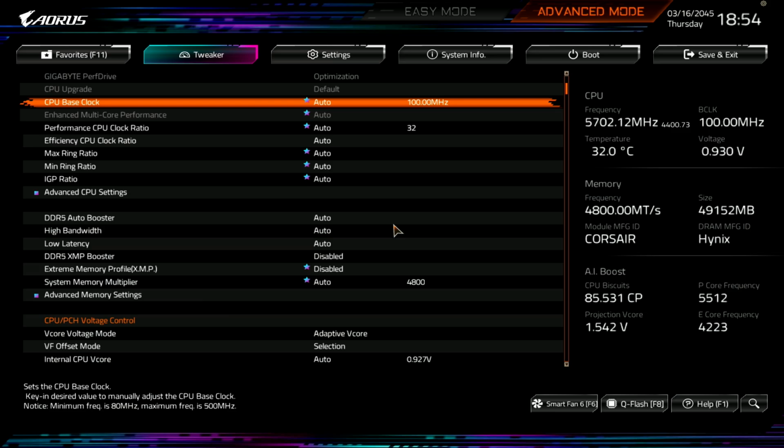But again, the one takeaway I want you to have from this video is that you don't need to turn off CEP to undervolt. If you're undervolting and CEP is ruining your performance, you're not undervolting correctly, basically. You should stop doing that and look for a different way to offset the voltage. As far as I know, every LGA 1700 motherboard that has voltage offsets available should allow you to adjust the vid offset, and that won't trigger CEP. So you should just use that instead of whatever you're using that is triggering CEP.